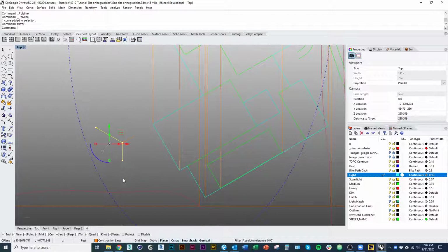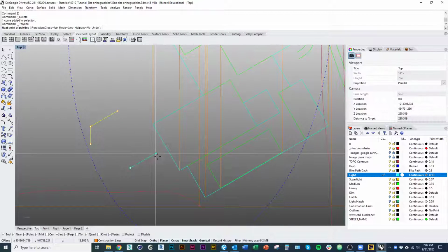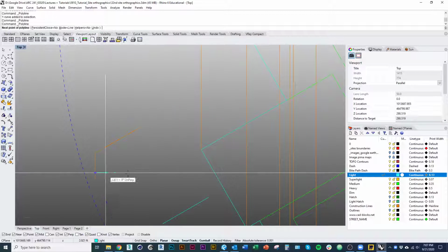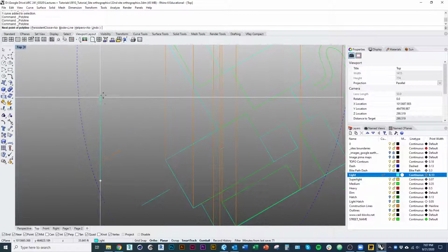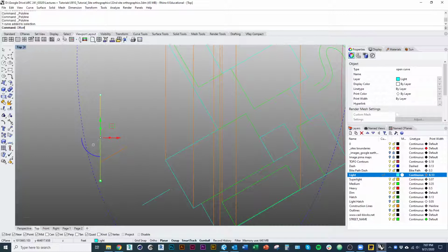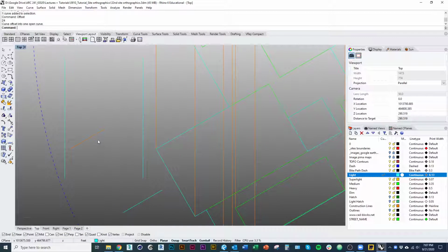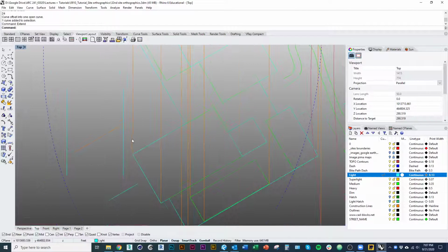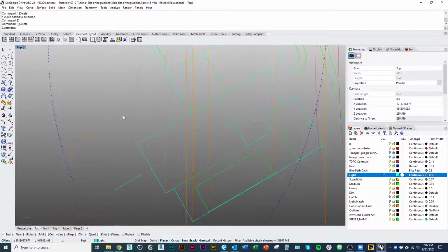So it looks like this, right? If we're looking at it this way, we're looking in this direction. At this roof piece, it looks like that, right? Except that, as you can see, it's 24 feet in depth. So I'm going to draw a line offset 24. Again, I don't want to change the roof pitch or the roof angle. I just want to make it longer, deeper, right? So I'll just use that line that I offset. These are 24, maybe a much taller roof, you can see.